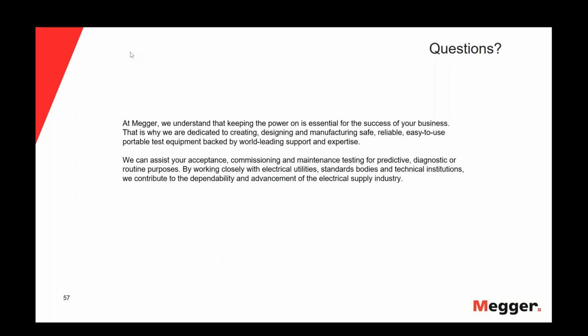Thank you, Henning. So Robert, are there recognized standards for the tan delta test value? Well, as Javier presented, there are the tables in IEEE 400.2. So for comparison and for the assessment in three categories, no action required, further study advised, and action required, by the three criteria: mean tan delta, stability, and tip up.